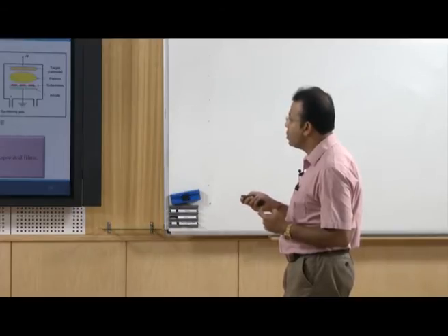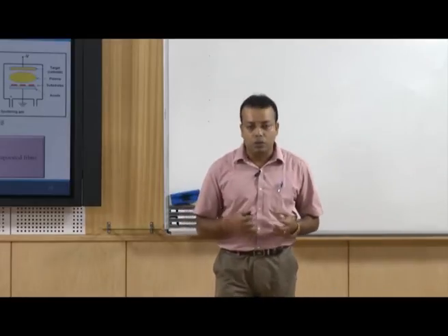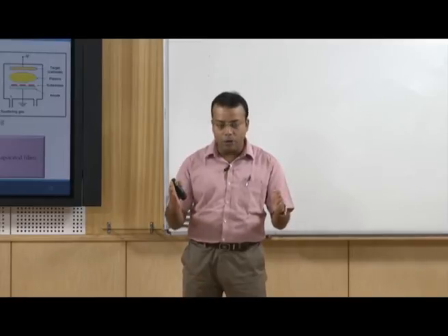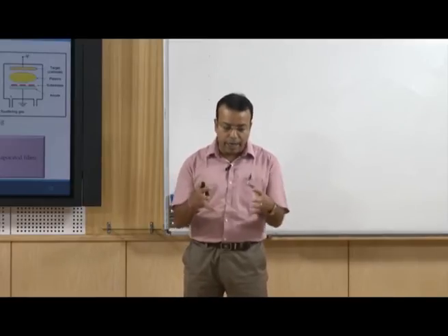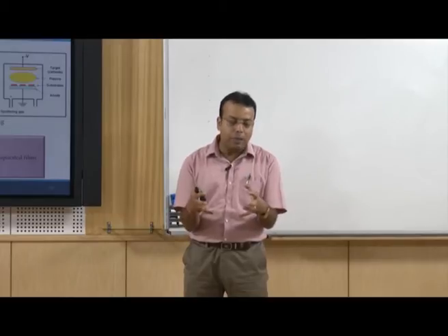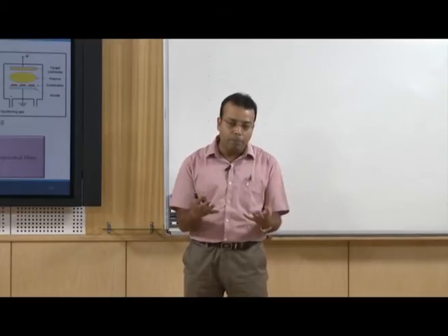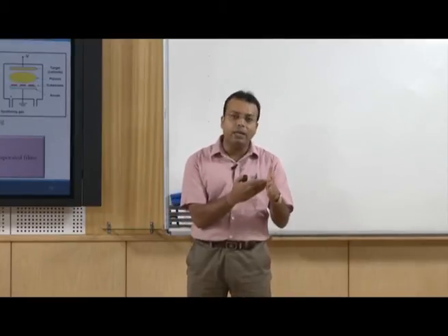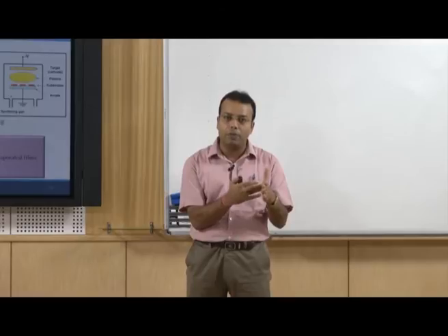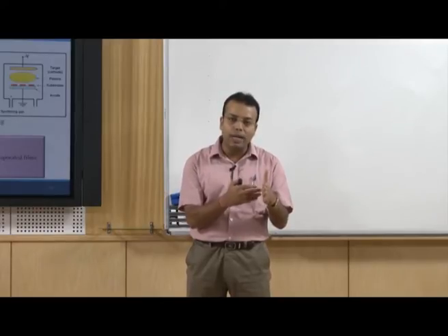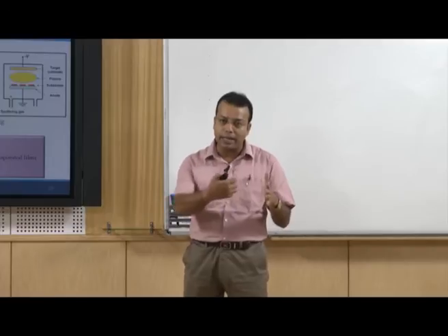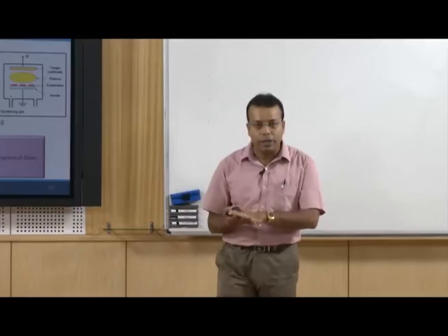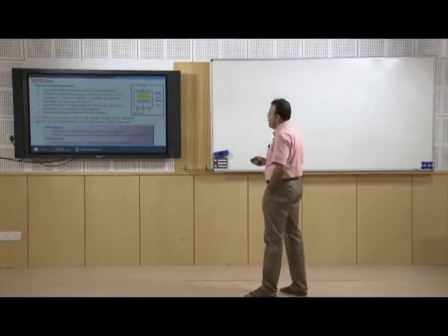Ejected target materials deposited onto the substrate itself. So, simply we are putting a certain potential difference between the cathode and anode, then we are injecting plasma, which comes directly from the argon gas. Then that plasma directly hits the target materials, or the source materials, and due to that, atoms or molecules come from the source materials and deposit onto the substrate materials. So, that is why it is called the sputtering technique.